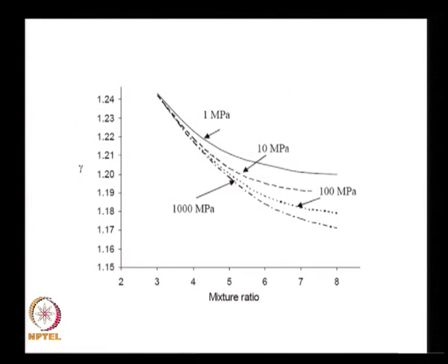Let us take a look at some more things. Let us take a look at gamma. Gamma, we said, for simple species like a monoatomic species was 1.67, for more complex things like CCl4 and all that it was lower, at 1.12 or something. And what do we find? We find that at higher pressure you have more complex products, and therefore the gamma is smaller. As pressure reduces, the value of gamma decreases, which is again in the right direction.